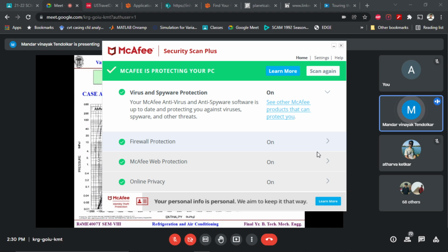Fine. So you can read the temperature T2 directly from the chart, so you need not go for the superheated part calculation using the thermodynamic equations. You can read T2, then H1, H2, and H3 equal to H4, isenthalpic expansion. And the specific volume you require, because your further calculation may be related to the compressor part. The density is known, take the reciprocal of that.